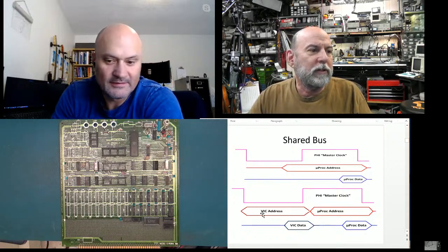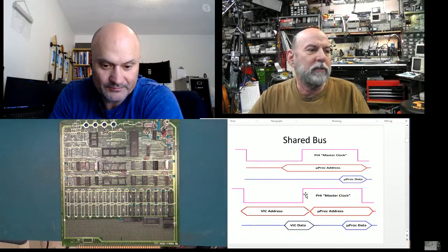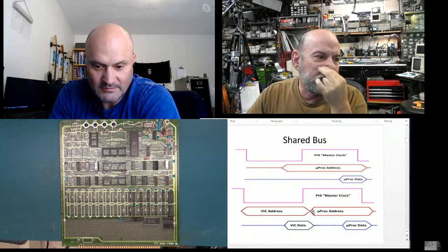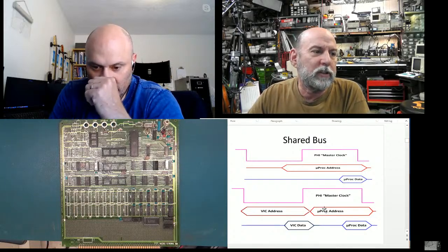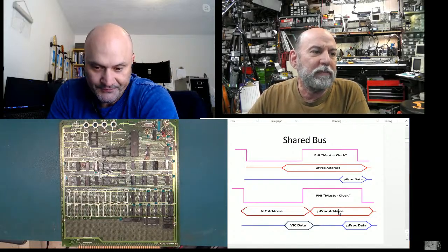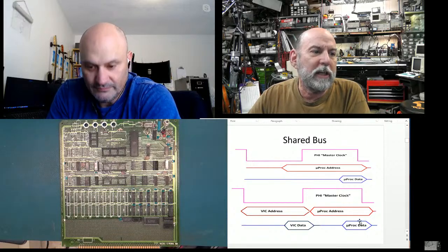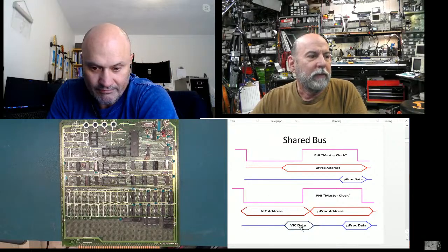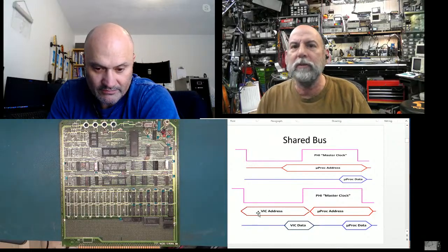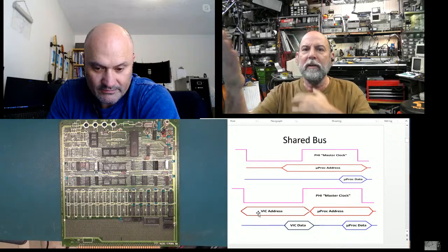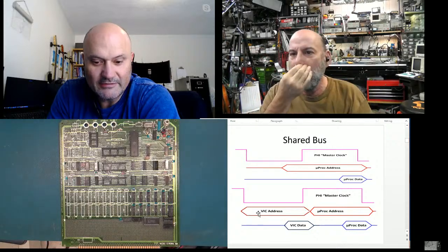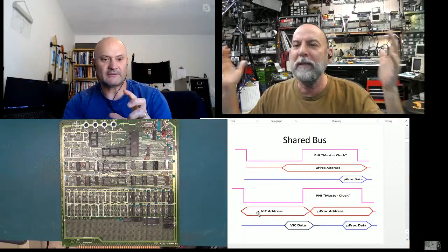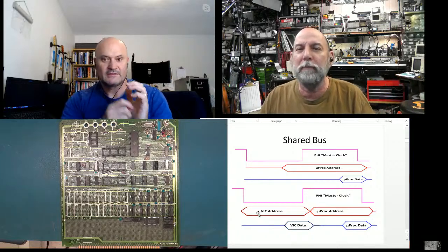So what we did is we said, okay, let's shorten things. We'll wait till phi high, and we'll spit the address out. It's now late, but we have enough time to still latch the data at the end of the cycle. And that left us with this other half cycle available that we used for the VIC address. So we interleaved: VIC, processor, almost every single cycle. Oh, it was wonderful. This was what made the Commodore 64 the best home computer ever made.